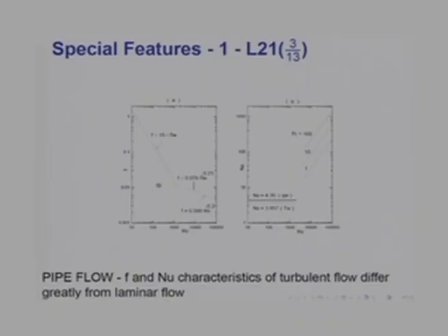Now, you will recall that the friction factor multiplied by Reynolds number is always a constant equal to 16 in a pipe flow, and therefore, on a log-log scale it will look like a linear line till about Reynolds number of 2000. Now, of course, the laminar flow equations do not know that the flow will turn turbulent or will change its character towards transition and then to turbulent if Reynolds number was increased.